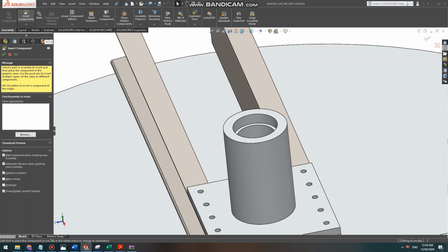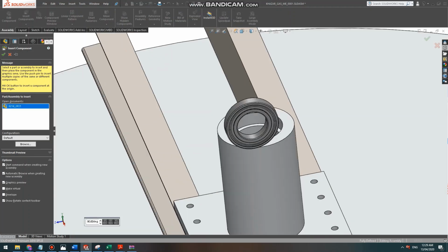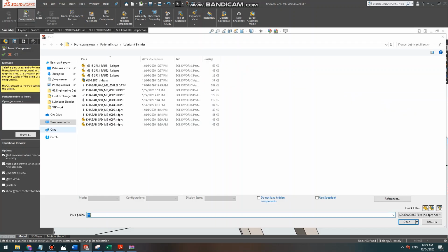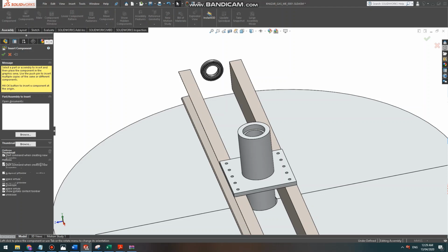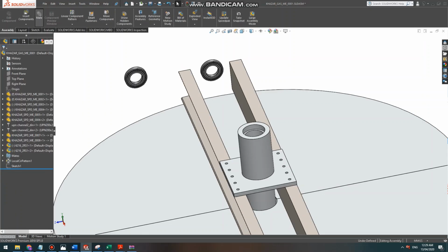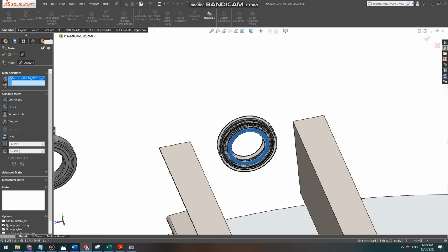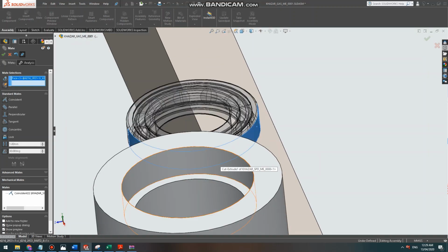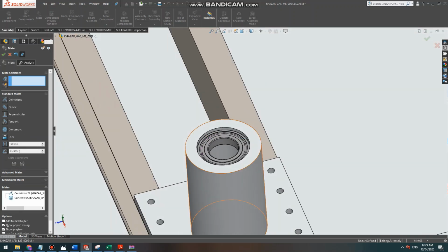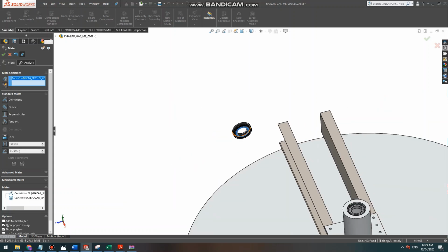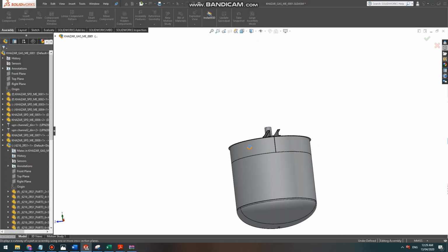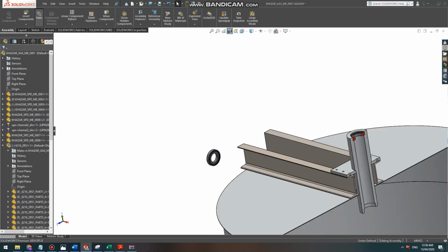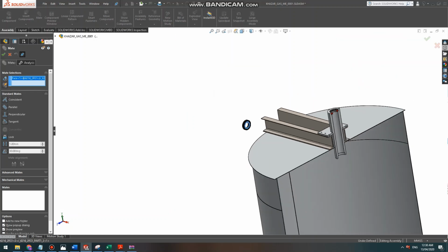Yeah, so we choose it, we bring it here, we look at the surface. It's okay, I'll do it like this one. I will do the other one as well. Then I will do the mate operation. This with this surface, perfect. And I also want this with this surface. That's the boy. So this is this bearing. I'm gonna do the other one as well, but for that I need a section view, which is this. Perfectly done. I made it now. This with this.